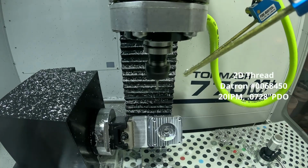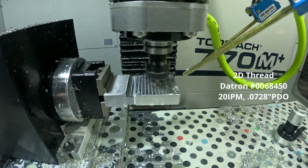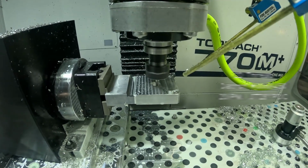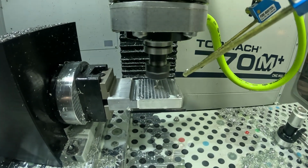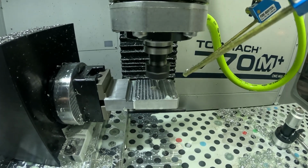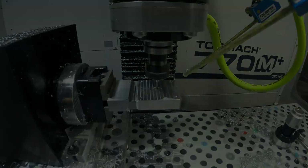Alright, here we go with the G14 threads. I'm using a Datron thread mill, 20 inches per minute. Took me a little while to figure out what thread mill to buy for the G14 threads, because they do have that 55-degree angle, and the only place I could find was Datron. It cost me a little over $100. If you guys know of a cheaper thread mill, let me know in the comments below.